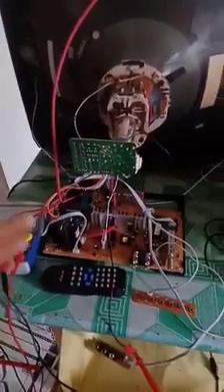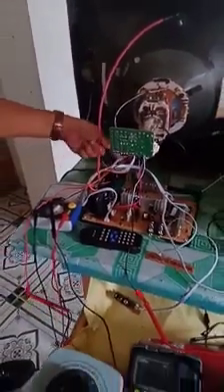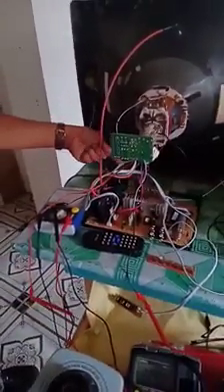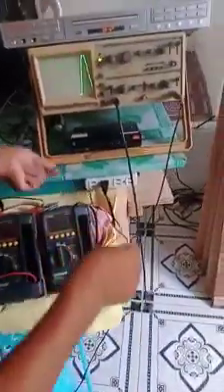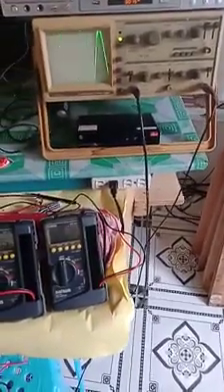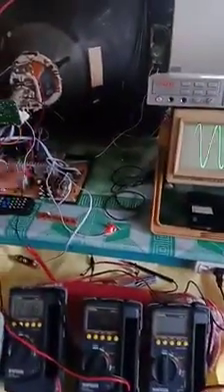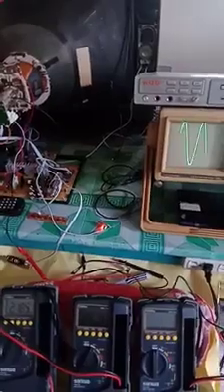Meaning to say that this capacitor is capable of storing the voltage up to the maximum level. And it is DC. It is DC because it is first rectified by the diodes before it is stored by this capacitor. Okay? And the third voltmeter will measure the voltages that are distributed to the circuits.